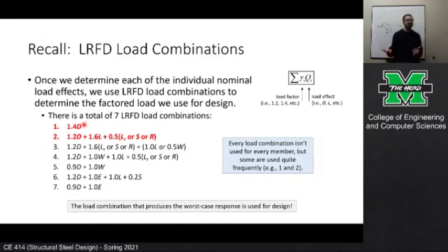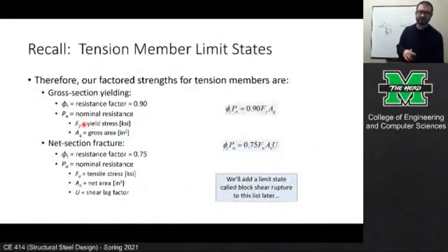Like, if I'm designing a school, it has to hold up the loads associated with the school, or same thing with a library or a fire station or whatever. So by its nature, dead load and live load are going to be very common. And as we said before, not every element in a structure experiences snow load. Like the floor beams in my office don't experience any snow load or wind load or whatnot, but some elements do. But just about everything experiences dead and live.